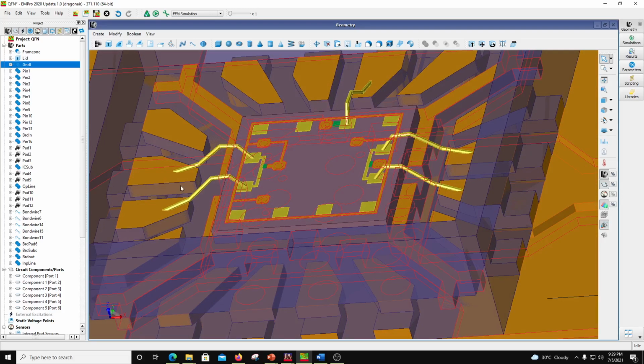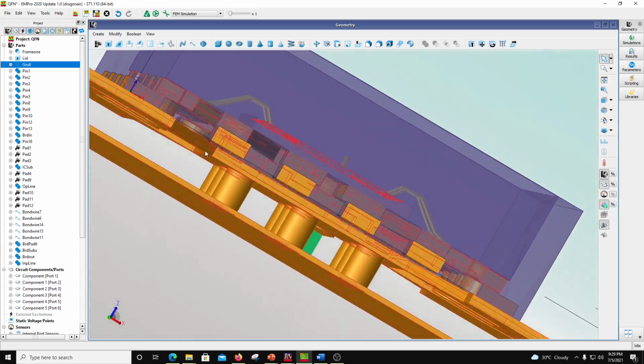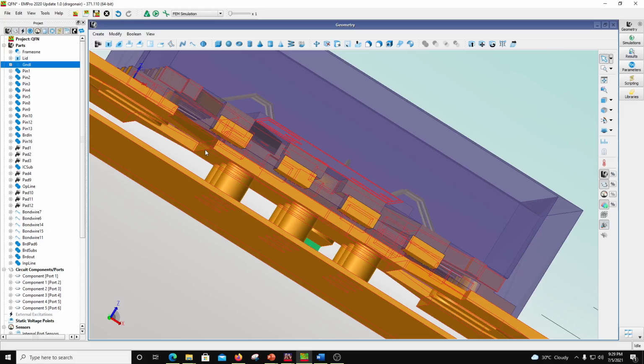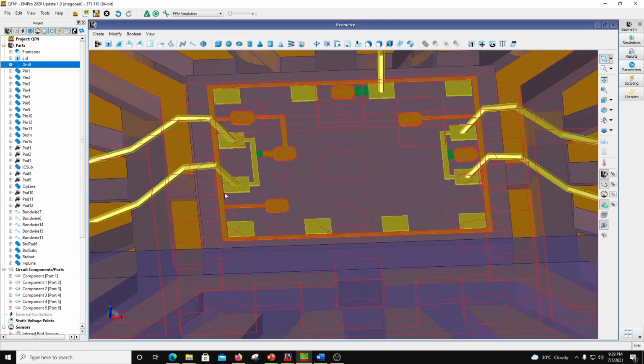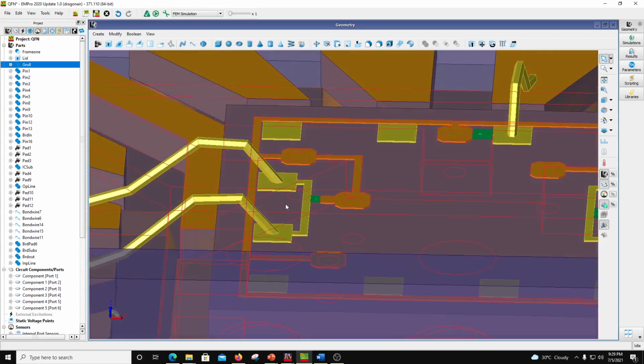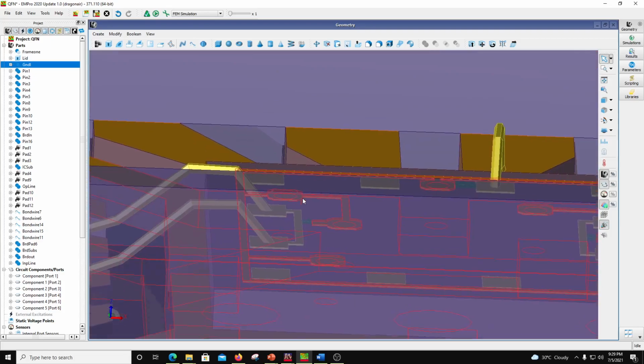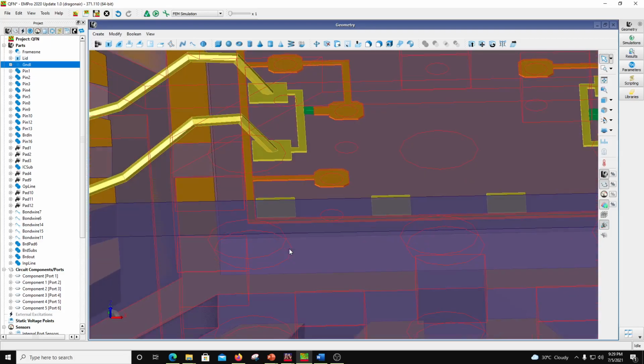And let me tell you, this C which is on the board side, it is of the order of 30 to 40 femtofarads, because the ground is almost 10 mil away or 5 mil away, right? While the capacitance here basically is going to be much larger for this bond pad, right? Because this bond pad is sitting on a substrate which is only 100 micron or 4 mil. So this capacitance is dominant, right?